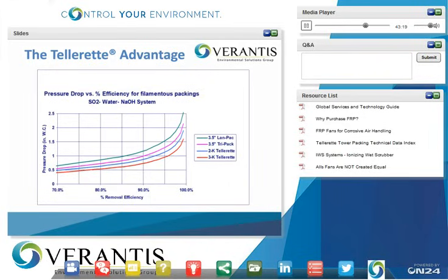So when you plot these out, in this case, this is a comparison of the 2K, 3K Tellerette versus the other styles of filamentous packing, the Tri-Pack and the Lanpac. You can see that for a given efficiency, the Tellerette K packings, both styles, will actually provide you the lowest relative pressure drop for that same efficiency.